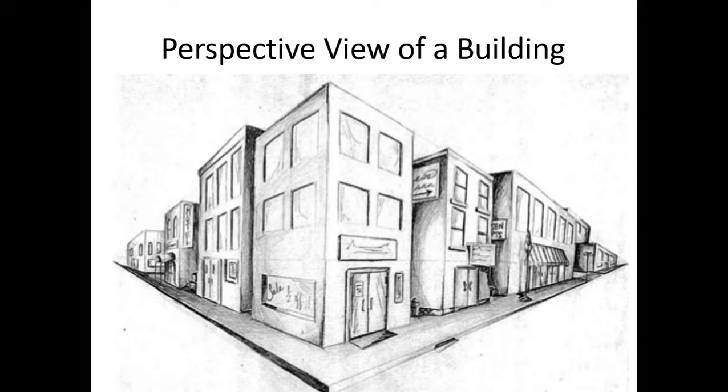Perspective projection is widely used by architects to show the appearance of the buildings before its construction. It is also used by production engineers to show the appearance of big machines for illustration purposes. Artists also prefer these types of drawings for preparing advertisement drawings. This is the perspective of a building. A person who is standing here, if he is viewing that object, he will feel that this side is taller than the other end. So this is his perspective.